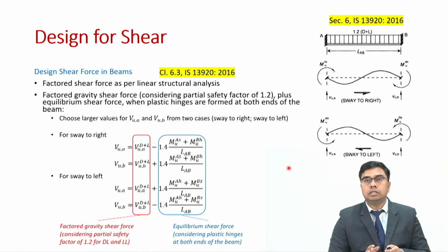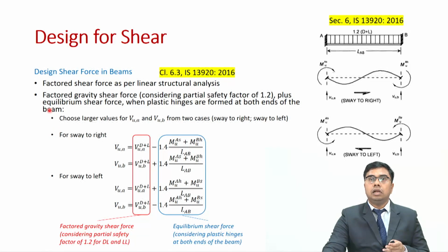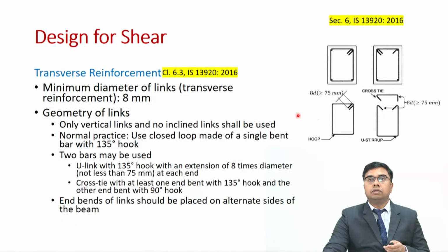Once you have this design shear force with you, you choose the larger value out of these two approaches, that is the factored shear force as per the linear structural analysis and the factored shear force based on this assessment. Once you have this, then you look into providing transverse reinforcement.